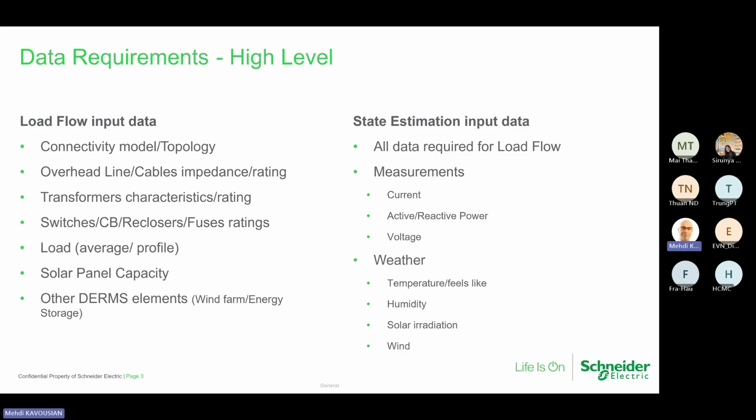So you have one energy storage, which is the battery. So that is for load flow, and for state estimation with all of this plus this, we could use current, active power, voltage, and as I said, better data.